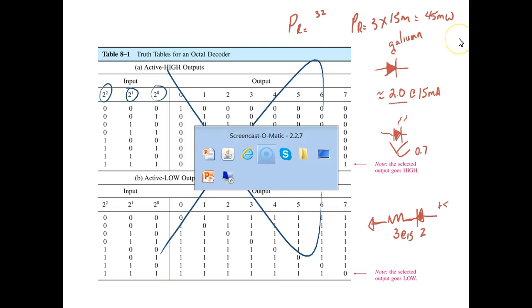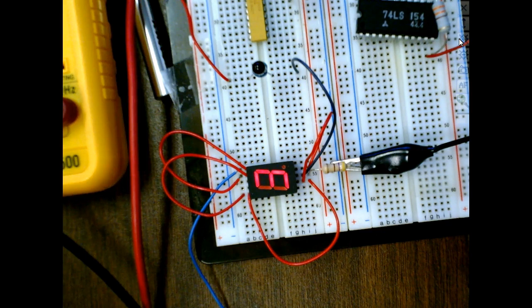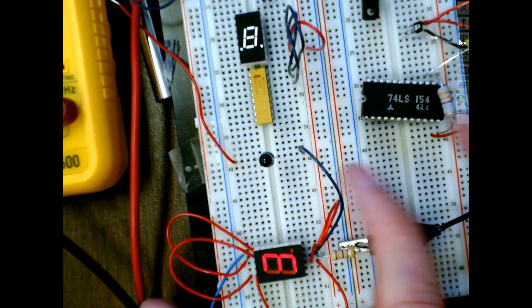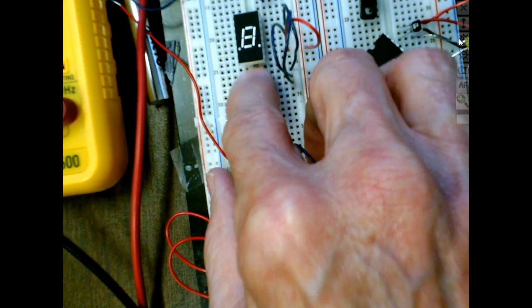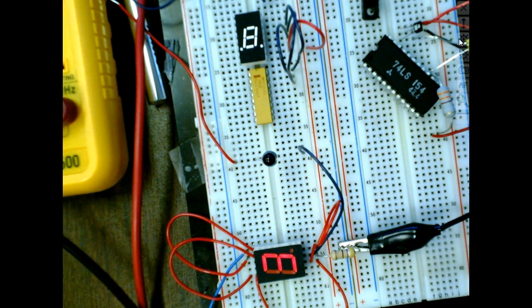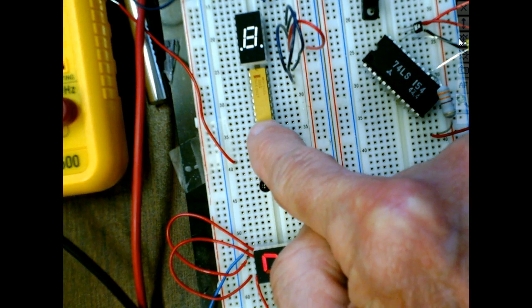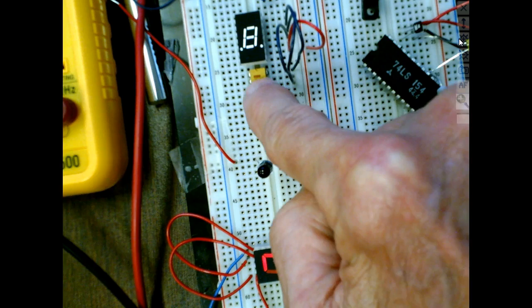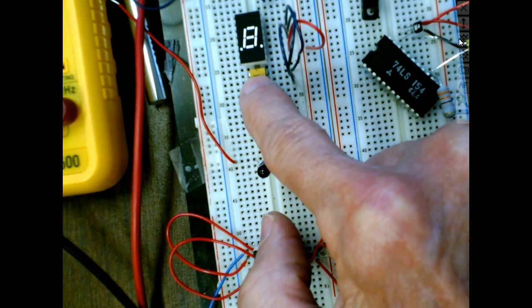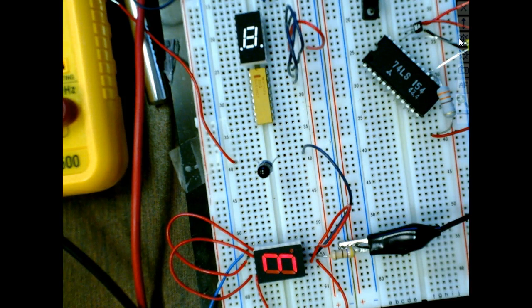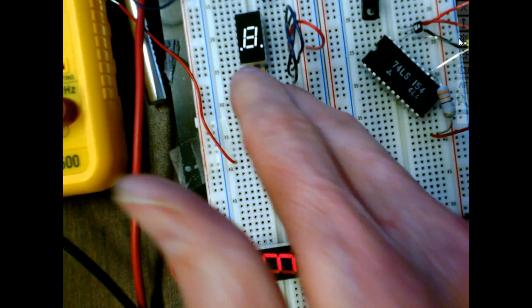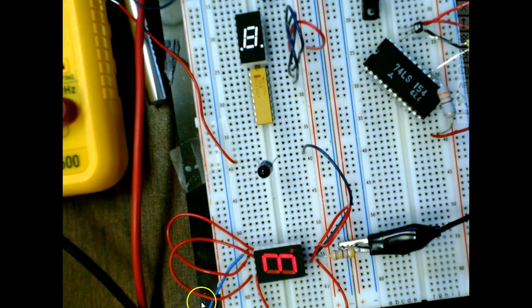Now this is a DIP. This would probably be better to do with a SIP. If you look at an IC and it's a weird color like blue, odds are these are not integrated circuits. These are just resistors. And how do you think the resistors would go? They just go straight across. This is a 16 pin, so I have a resistor between pin 1 and pin 16. You don't power up resistors, right? They're just resistors. So this is a resistor pack. We have what they call SIPs. So these are DIPs. What would you think a SIP would be?